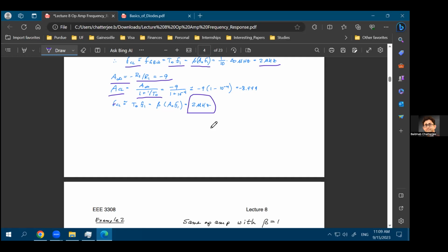So basically, like having an op-amp with a feedback, you operate with increased bandwidth. Yes. Gain reduces, bandwidth increases. If you go back to feedback theory, I think it's also covered in Circuits 2 lectures, it explains from equations why your gain reduces and why your bandwidth increases when you have negative feedback. More questions?